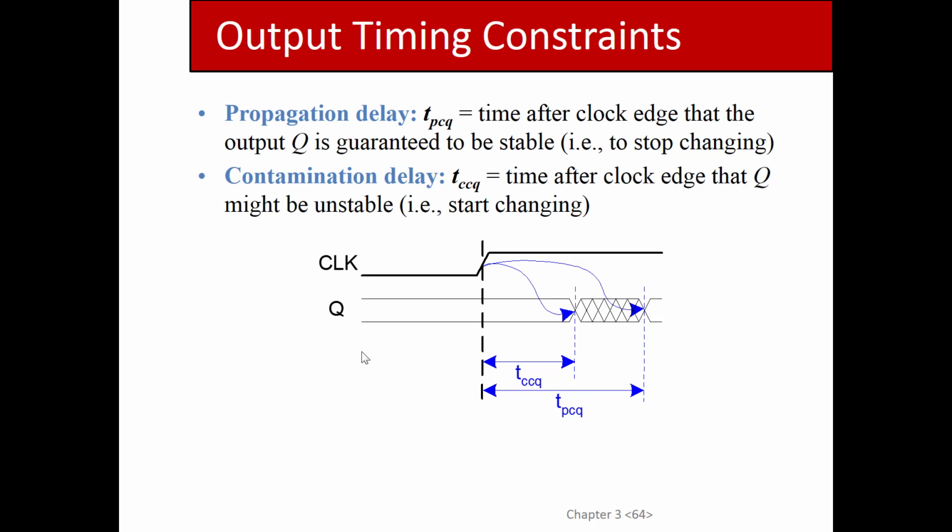They will be characterized, and the characterization data will include the contamination and the propagation delay of the flip-flop. We used to have a class here, 613, in which we would actually run a tool called Signal Storm. Was that Cadence? Cadence Signal Storm. That tool would actually take your library and figure all this out for you.